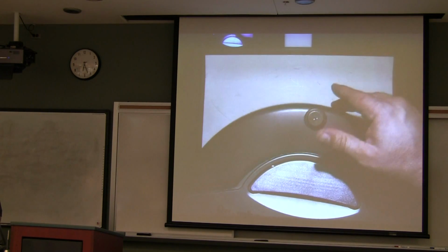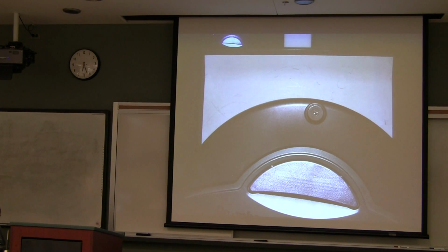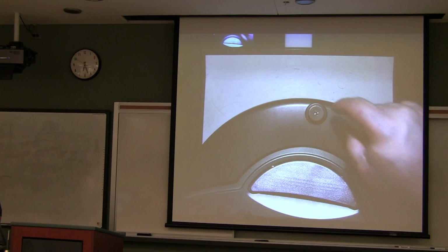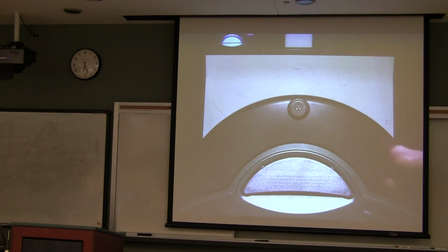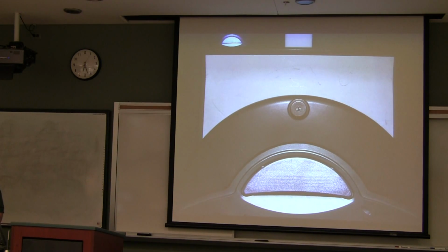sensor on top. What do you think that's for? It's a bump, yeah. So these things used to go full power right into the wall. And the newer versions came out that it actually would use a sensor on the front. They're not on these. That would detect when you're getting close to the wall and would slow down before you hit the wall. This is infrared that is actually used for communications to go to its charging station, as well as they have a technology called a virtual wall. So if I wanted to vacuum one room, let's say you have a house that has a living room but no door to it, and you want to only vacuum that one room, you could put up a small little lighthouse, they call them, and basically block off the entrance to that room so the robot would stay inside there.